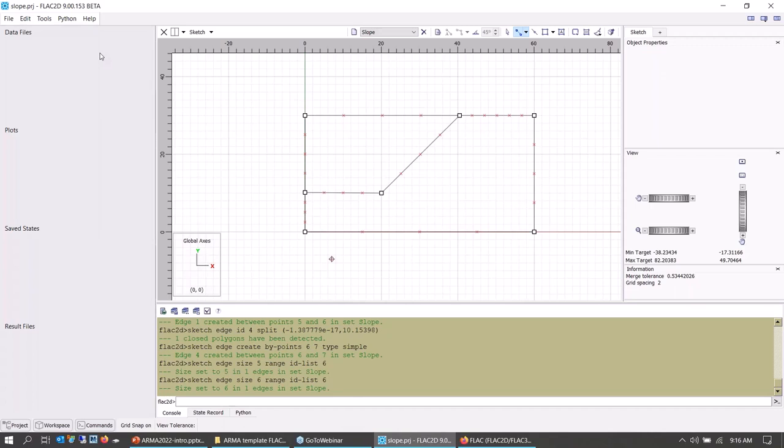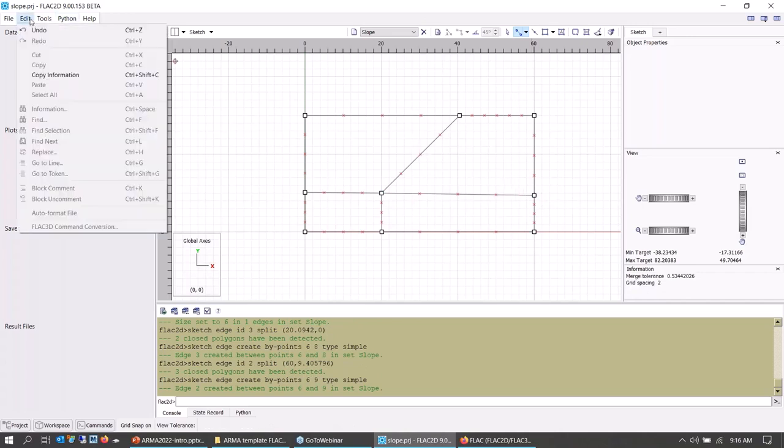Even though it's possible to make these unstructured meshes, it's still better to have a structured mesh. You generally get better results. And for a simple problem like this, it's relatively easy to make a structured mesh. All you need to do is create 4-sided shapes. So to do that, I just need 2 more lines here. I'll draw one from here down to here, and one from here down to here. Oh, see, I missed there, so I'm going to undo.